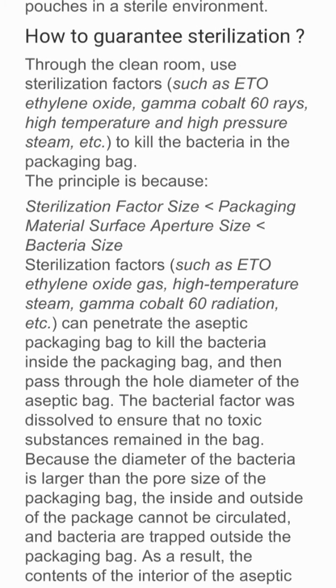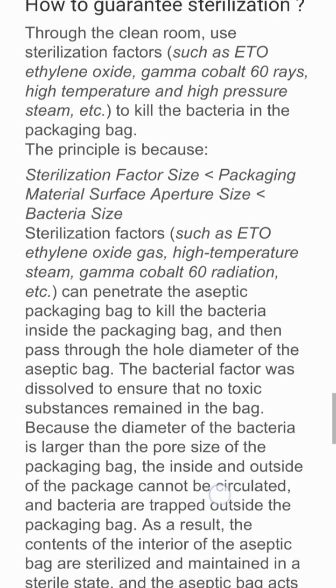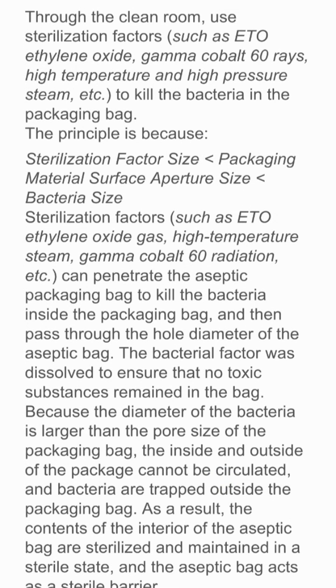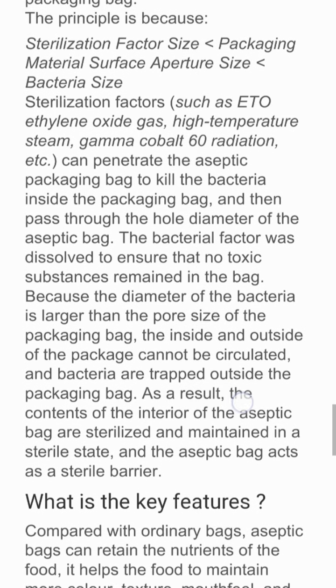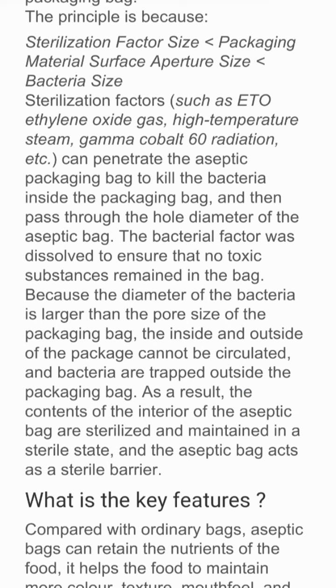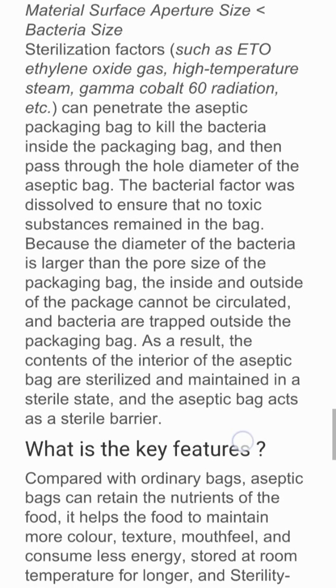How to guarantee sterilization? Through the clean room, use sterilization factors, such as ethylene oxide, gamma cobalt 60 rays, high temperature and high pressure steam, etc. to kill the bacteria in the packaging bag. The principle is that the sterilization factor size is less than the packaging material surface aperture size, which is less than the bacteria size.